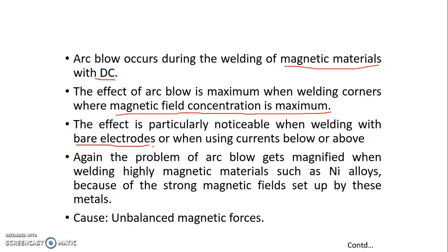This effect occurs when the electrodes are bare electrodes or when using currents below or above the recommended range, then these types of effects occur in DC welding.